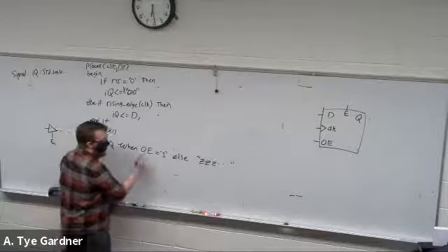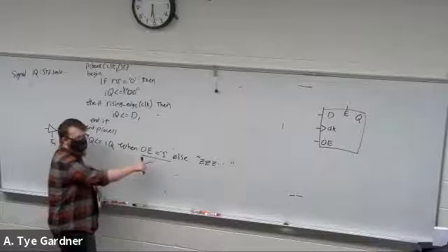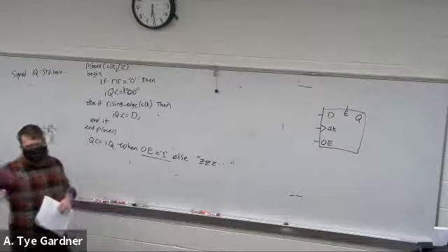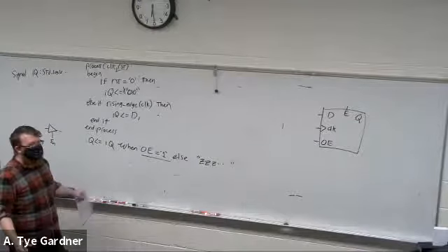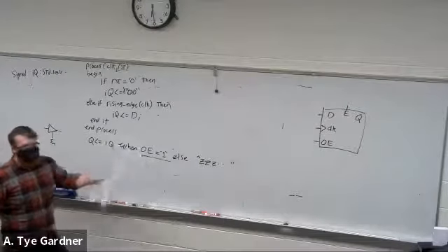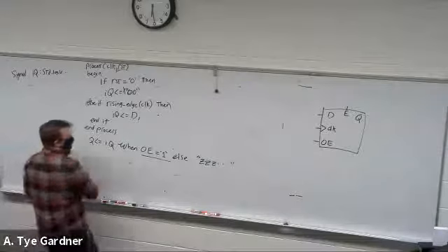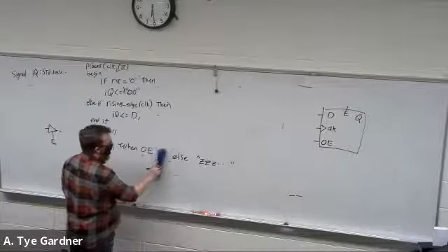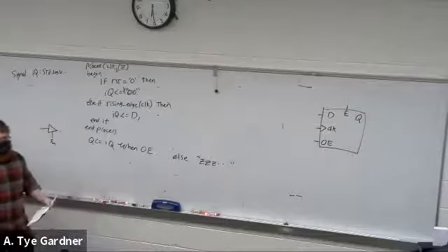We do need this whole thing that says when OE equals 0 because we're standard logic. Because standard logic can be 0, 1, Z, H, L, right? It can be lots of different values that we haven't really gone into depth. If we were dealing with just strictly bit types, if OE was a bit type, you could do when OE, because a bit is strictly 0 or 1.